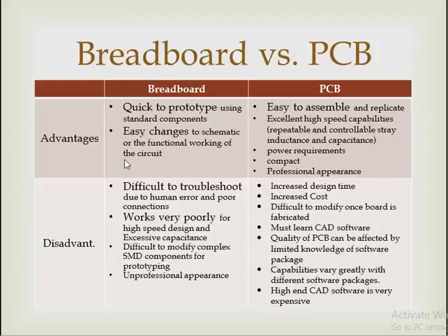Breadboard versus PCB. Breadboard advantage: quick prototype using standard components, easy to change the schematic for the functional working of the circuit. Disadvantages of breadboard: difficult to troubleshoot due to human error and poor connections. Works very poorly for high-speed design and has excessive capacitance. Difficult to modify complex assembly components for prototyping, and unprofessional appearance.